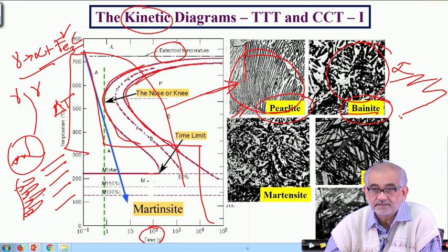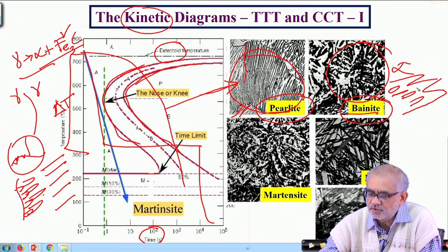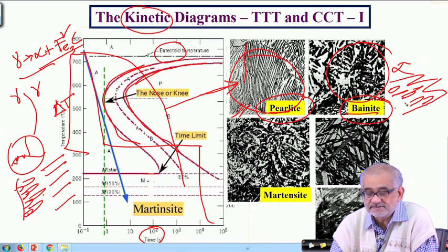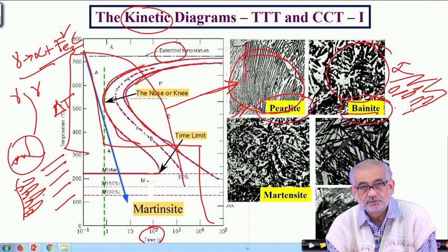So these are like palm leaf type of a structure, and when such a ferritic sheaf nucleates, the excess carbon is rejected, and those excess carbons nucleate as small stringers or in the form of platelets, either between two such consecutive sheaves or embedded within the sheaves. So accordingly we get sort of upper and lower bainite.